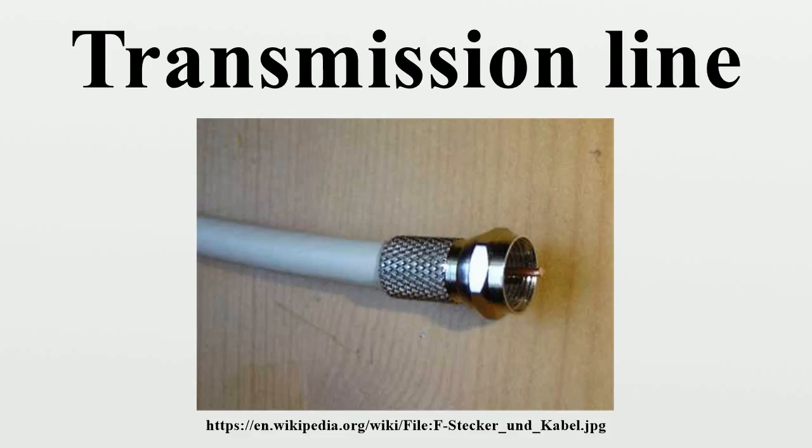Microstrip. A microstrip circuit uses a thin flat conductor which is parallel to a ground plane. Microstrip can be made by having a strip of copper on one side of a printed circuit board or ceramic substrate while the other side is a continuous ground plane. The width of the strip, the thickness of the insulating layer and the dielectric constant of the insulating layer determine the characteristic impedance. Microstrip is an open structure whereas coaxial cable is a closed structure.